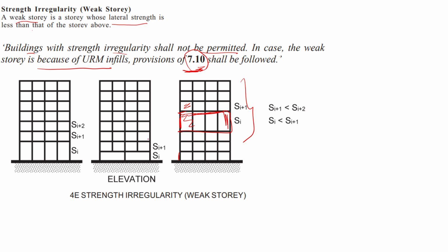And normally what structural engineers suggest, from an earthquake viewpoint, is that in zones 3, 4, 5 and all, it's better not to have irregularity. We should make sure that it won't be in an irregular shape or something like that. So make sure on that.